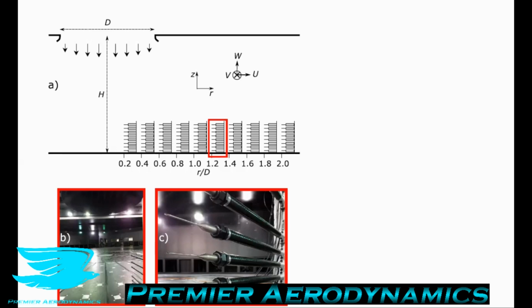If you take an experiment and you do it once, and let's say you're measuring the force, and you get a force of 5 newtons, and you have done an error analysis of your load cell or whatever you're using, and you know that it's 1% plus or minus the uncertainty. If you then do another 3 measurements, you can then drop that random error by a factor of 2. So you can halve it because it's the square root of 4, which is the number of measurements that you've taken. If you do 9 measurements, the square root of 9 is 3. So you can drop that uncertainty by a factor of 3.